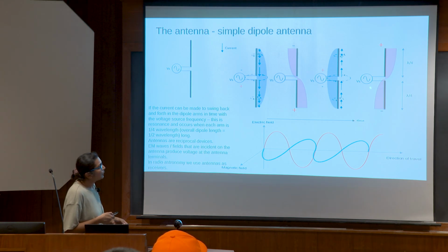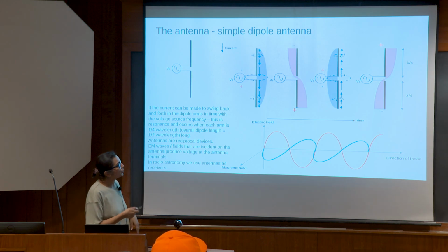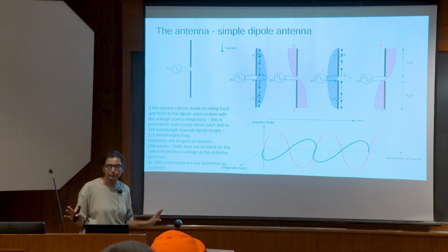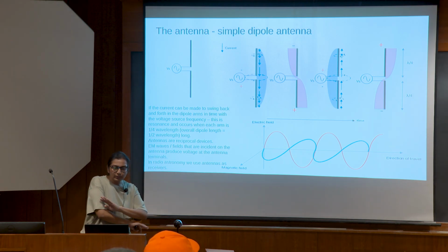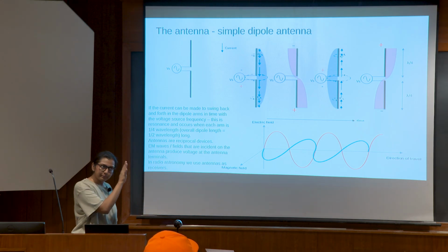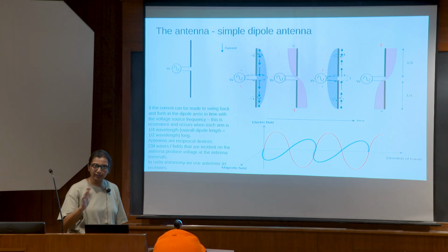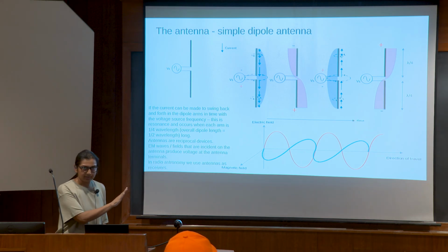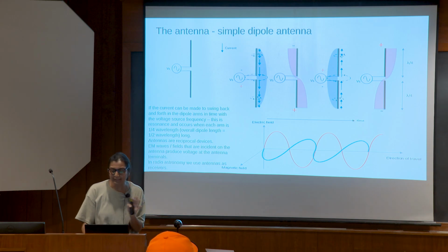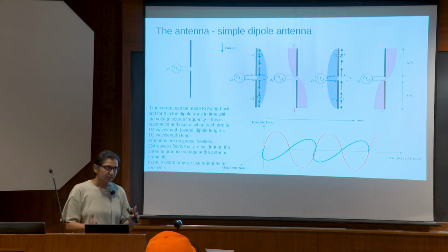It is resonant when the arms of the dipole are lambda by 4 each. Hence the total length is lambda by 2, or a half wave dipole. I will not touch any more on details of antenna because there are many types of antenna, but the principle of operation is the same. It either transmits or receives electric and magnetic field lines like this. Mostly electric, magnetic we don't really talk about, it's more in terms of the polarity of the signals.